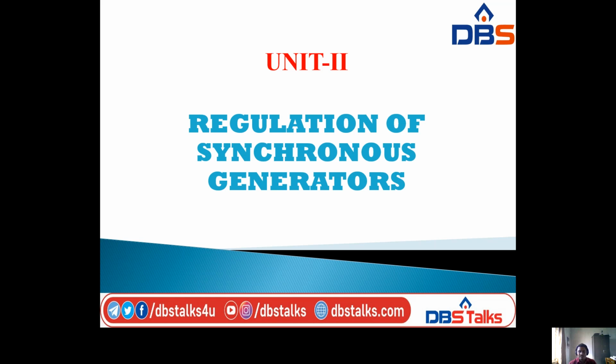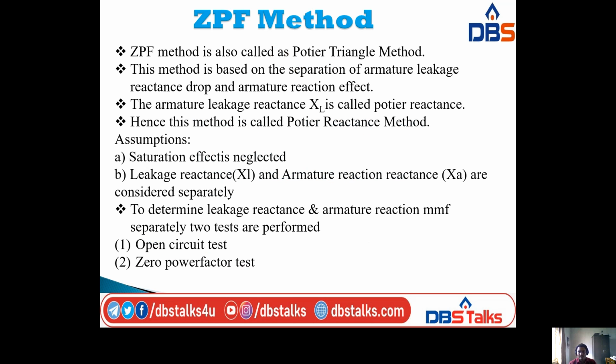Coming to the topic, the ZPF method is also called the Potier triangle method. This method is based on the separation of armature leakage reactance drop and armature reaction effect. The armature leakage reactance XL is called Potier reactance. Hence, this method is called the Potier reactance method.